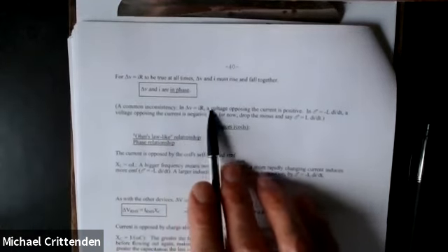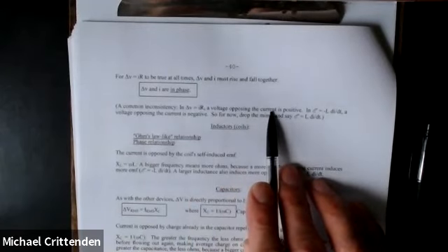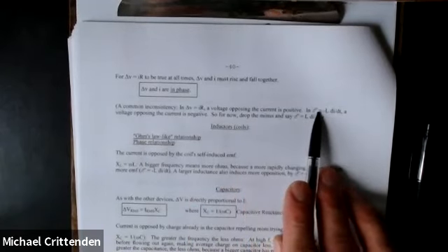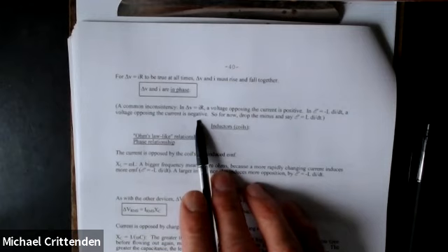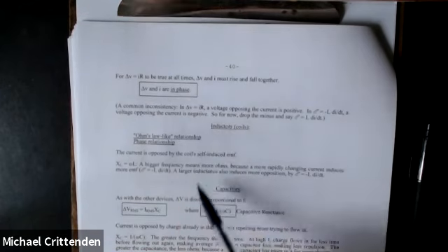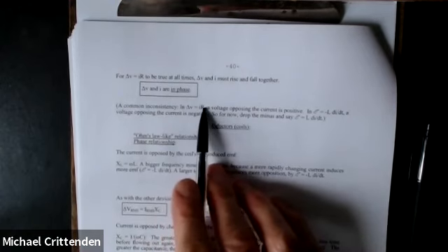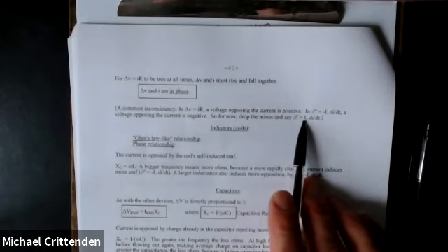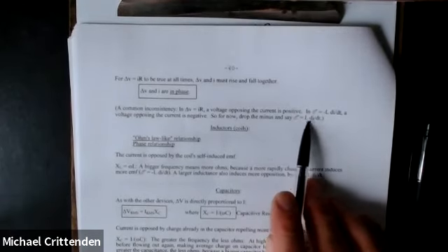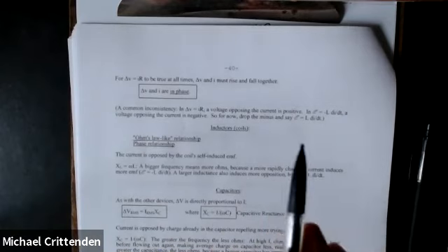When you say V equals IR, you're saying that a voltage opposing a current is positive. When you write this, you're saying that a voltage opposing the current is negative. So it doesn't really matter which way you do it, but you've got to be consistent. And the way all the rest of this is set up, we're going to do it based on V equals IR rather than V equals negative I times R. If you're going to do that, you've got to lose the minus sign out of Faraday's law and things like this that follow from Faraday's law. And so with that in mind,